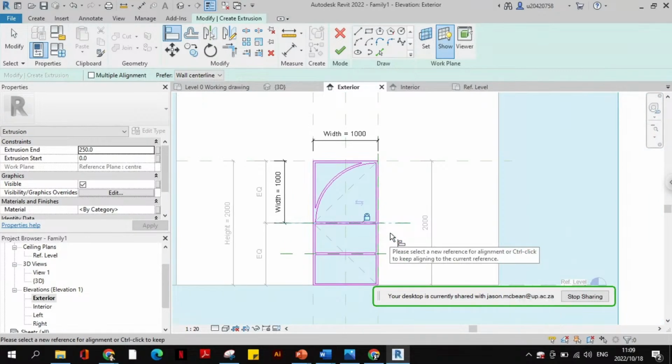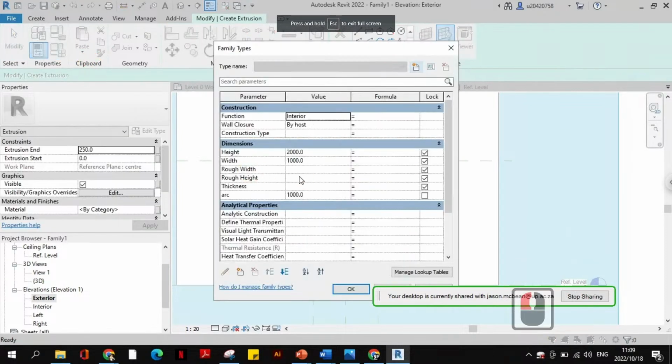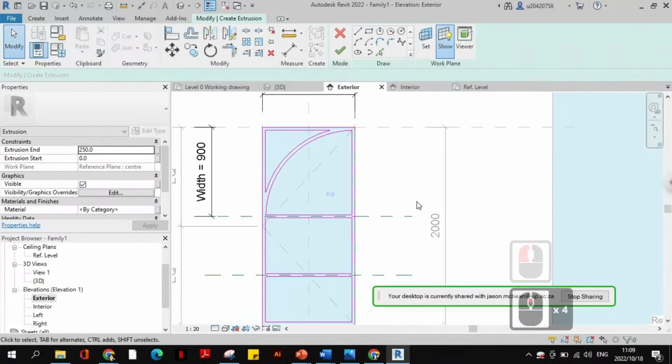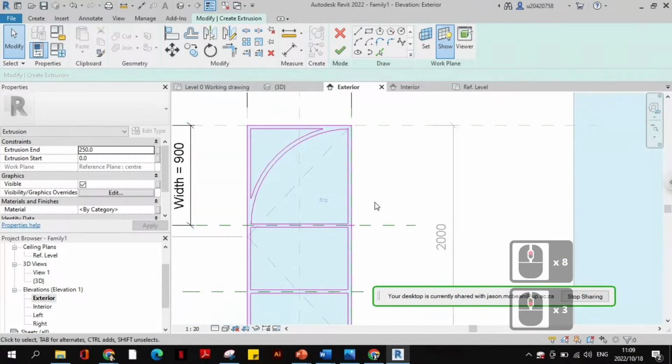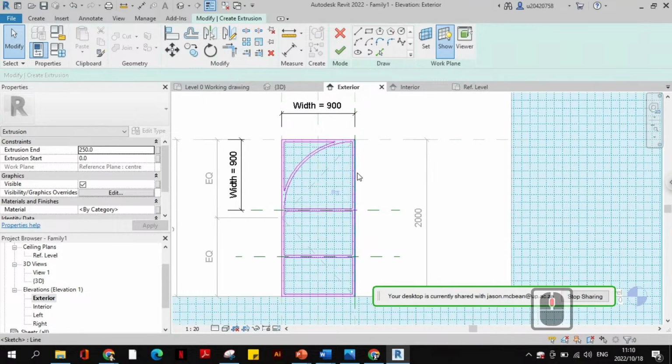If the door gets narrower, and watch this, now the magic is going to start to happen. So now, if I change the door width to 900, it maintains. All hell can break loose if you don't get this correct. You'll see the door will actually stop working.